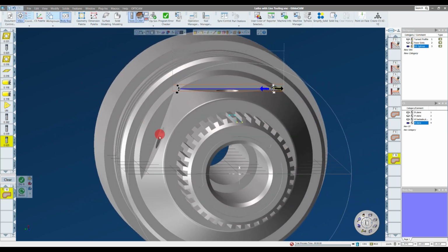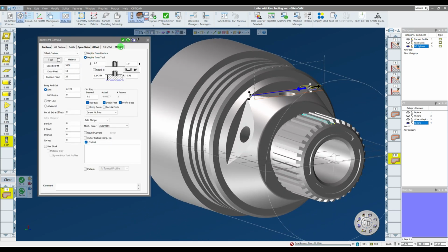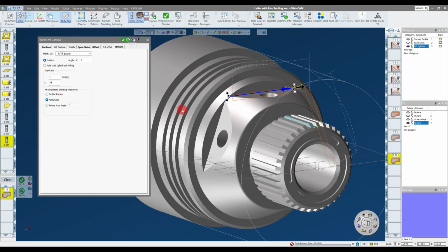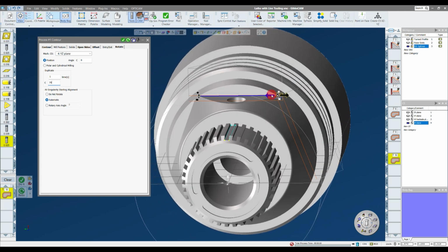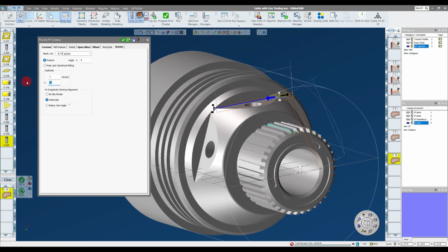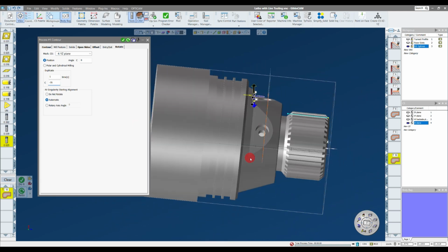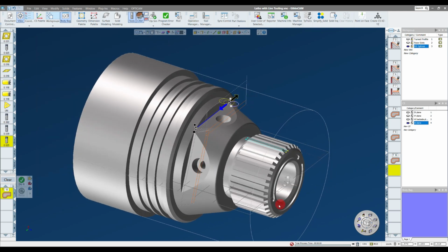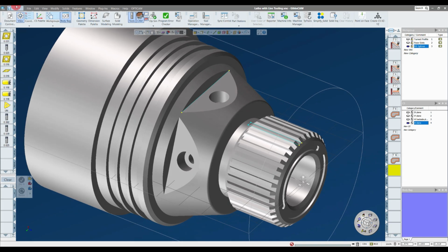And if I want to machine the second slot at this angle, I know that's a 70-degree angle. I can go into there, go to my rotate tab, and I can duplicate this 1 time. And if I put in 70 degrees and redo, it's like, oops, 70 degrees is the different direction. So I would just simply go ahead and change this to a -70. Redo, and now I have both of these flats oriented properly. All right. So we're getting close to the end of this part. I'm going to go ahead and file save. And let's work on the holes of the part.